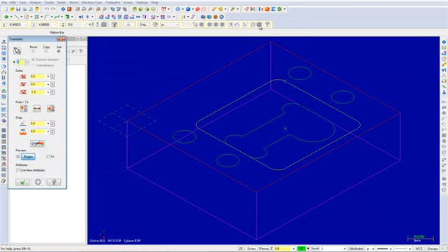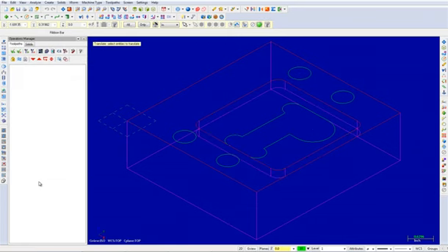In the Translate dialog box, enter a delta Z value of -0.25. Also, ensure that join is still enabled. Select the Apply button to stay within this command. Your part will appear as shown. Again, holding the Shift key, select the following shape. Choose the End Selection button.